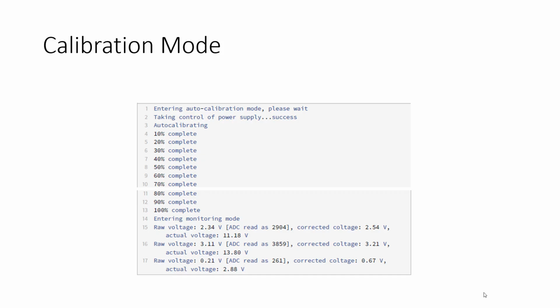It's not normally something you do with a bench power supply, but we're going to do it because we're going to sweep through this calibration range. That actually brings up an important point. Don't go over 14 point something volts. Don't set it higher than that because you can fry the board, because that'll take a pin over 3.3 volts. So cap it there. Don't go any higher.